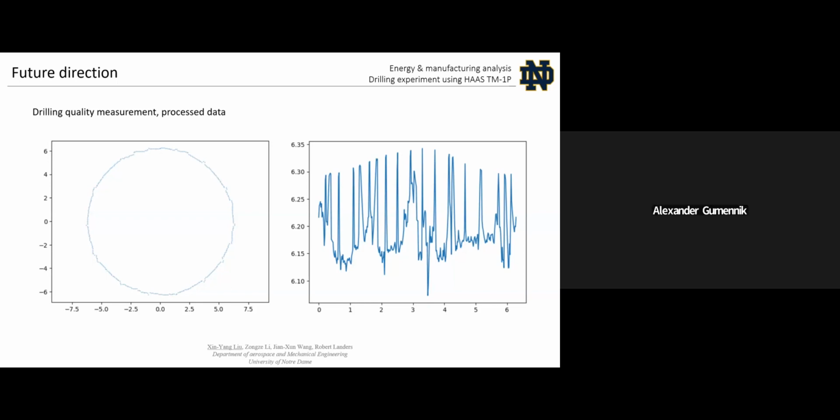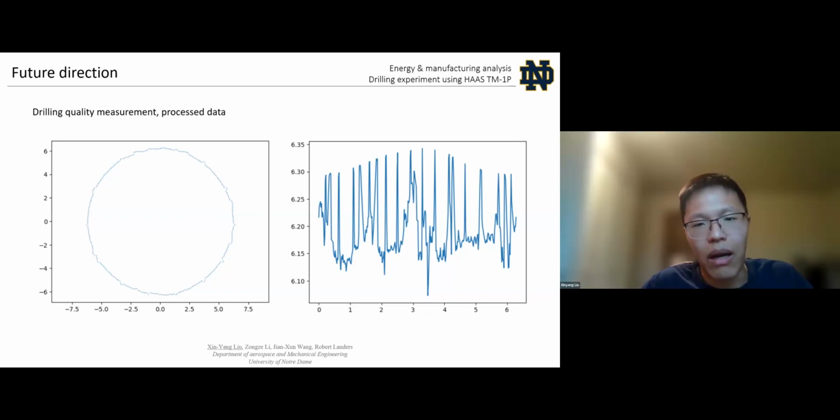What you say is right? The drill cannot result in an elliptical hole. It will have an exactly round hole. The fact that you have an envelope that looks like a sinus means that you measure an ellipse. Otherwise, you would be measuring an exactly straight line. Okay, yeah, maybe, but not sure.